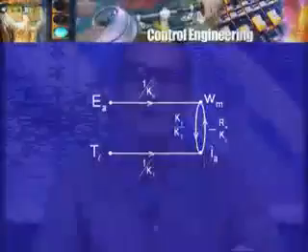So, that is my signal flow graph for the armature speed control problem, where we had only applied armature voltage and no feedback. The scheme was really very simple. Now, what was the goal of all of this? We wanted expressions for omega m basically, and perhaps Ia also, in terms of the applied voltage and the load torque, to find out how the speed will change if the applied voltage changes or if the load torque changes from the nominal or the rated value. Now, we will use Mason's rule for this purpose, and as you can see, the graph is very simple. So, the application will be very easy.